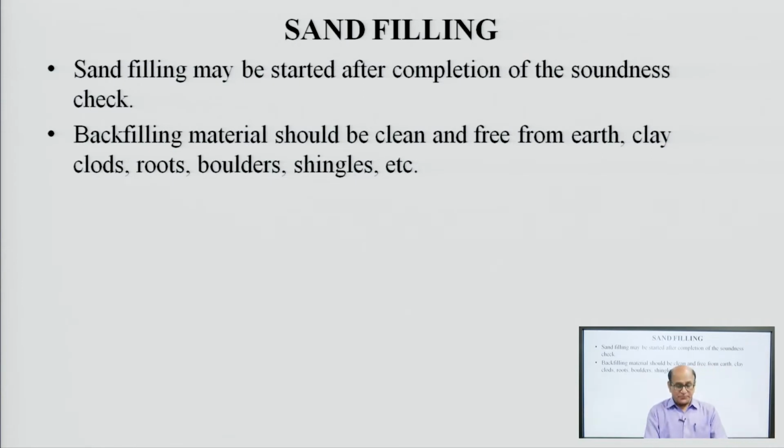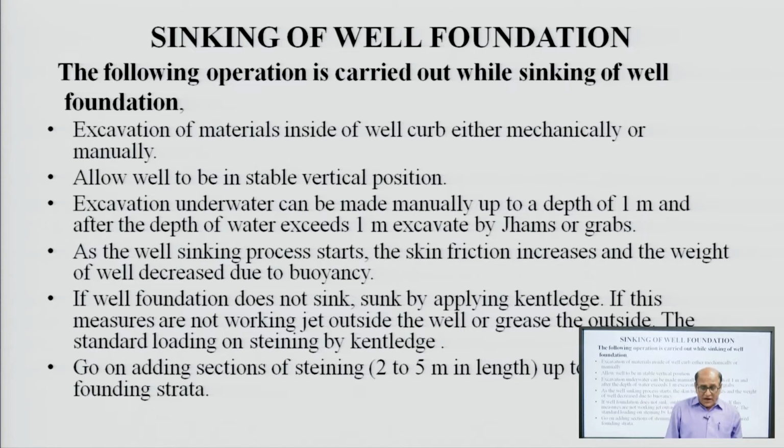Sand filling may be started at the completion of the soundness check. Backfilling material should be clean and free from earth, clay and clods. Sinking of well foundation: the following operation is carried out while sinking the well foundation. Excavation of material inside the well curb, either mechanically or manually, allows the well to remain in a stable vertical position.